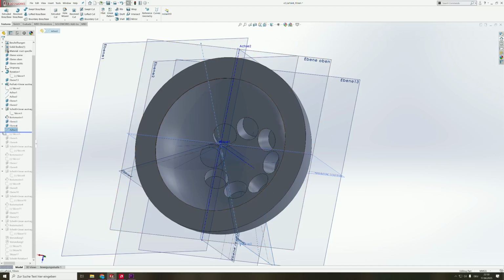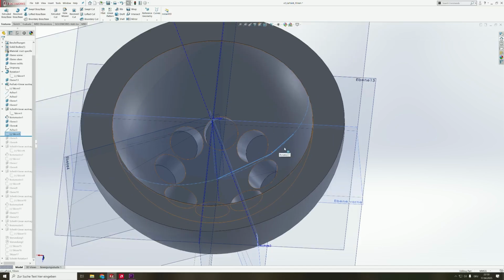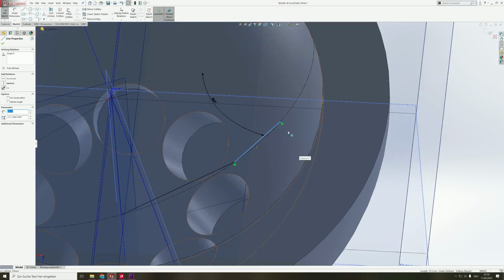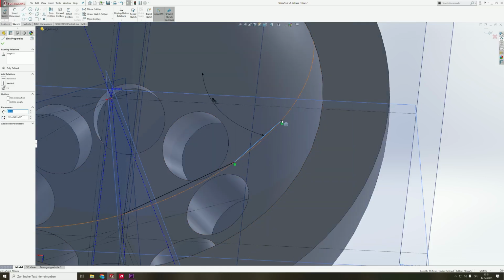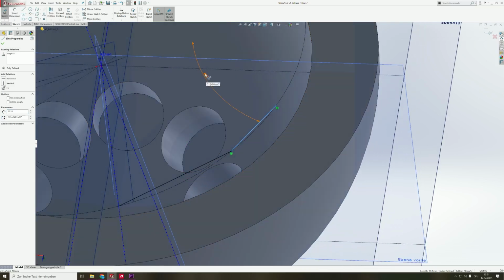The reason why I did this is just like I said before, I want the next row of holes with an offset, so the magnets can be placed as densely as possible. And here I just made another sketch. Let me just show you this one. Also, I drew in a line here with 10 millimeters length, and I just assumed the position again. And yeah, you maybe have to try and correct it again if the position is not correct. And this line will help to determine the angle.